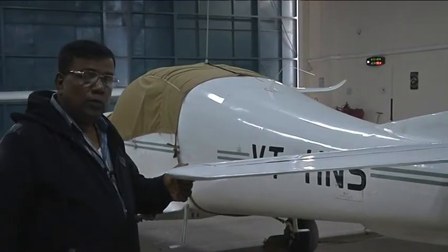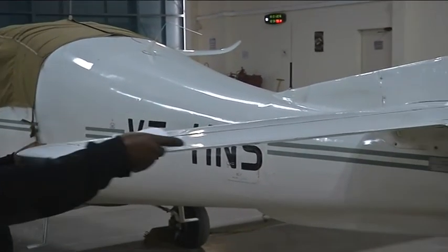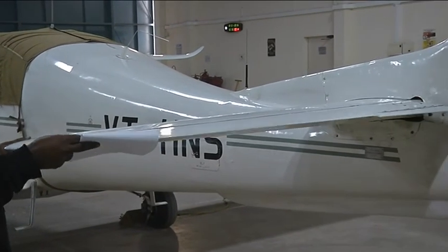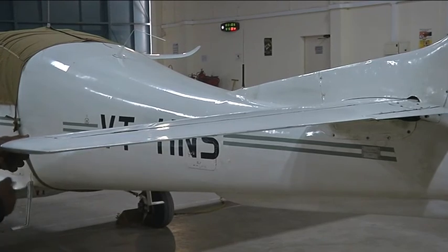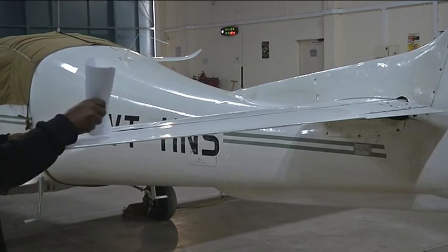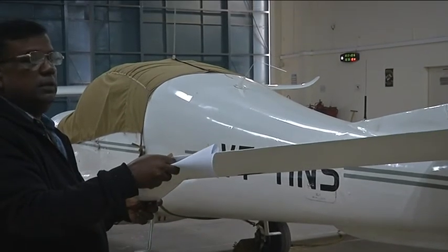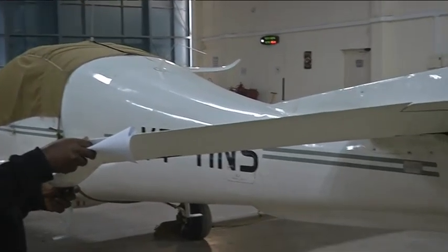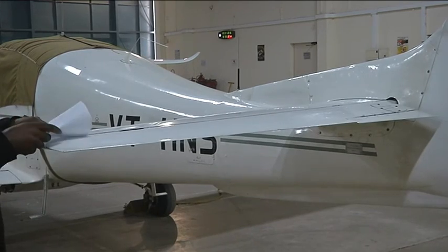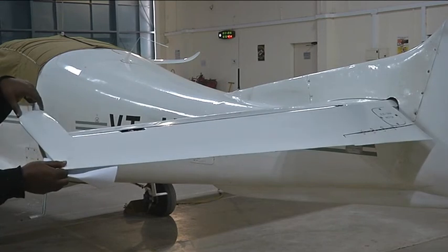We are discussing the floating tendency of the elevator. You could see this is a Hansa 3 aircraft, and these are the elevators, and this is the hinge line about which the elevator rotates up or down. Now if there is an alpha T, you could easily see that the center of pressure on this elevator will be somewhere here and the hinge line is here, so it will have a floating tendency like this. Clear or not? Now in a normal aircraft, the elevator is only up to this portion, but here you see an extension has been put, and that is part of a horn balance.